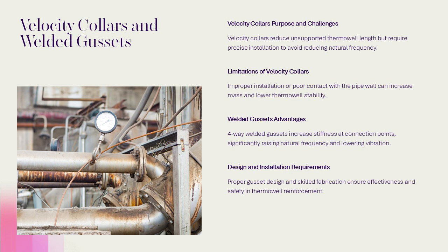A more reliable solution involves using 4-way welded gusset plates on thin-walled pipework. These gussets increase stiffness at the Thermowell connection point, significantly raising the natural frequency and reducing vibration risk. The effect of gussets can be predicted using the wall thickness modifier FM. Proper design and installation of gussets requires skilled fabrication and adherence to engineering standards to ensure effectiveness and safety.